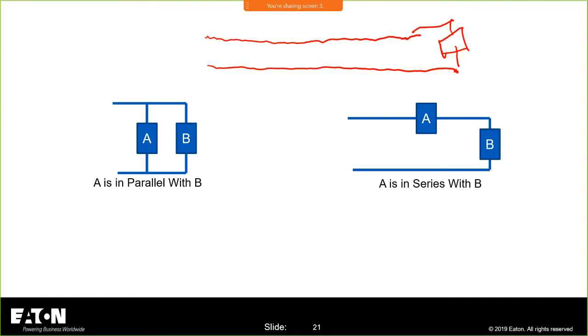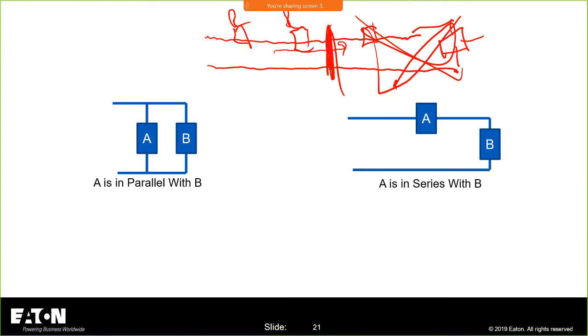We drew this out and showed the impedance of all the different conductors, maybe terminal blocks, and all of these were resistances. We said the normal load current was a very low value because of whatever the load is drawing, but the moment I had a short circuit, the load was taken out of the picture, and now my circuit current is much higher.